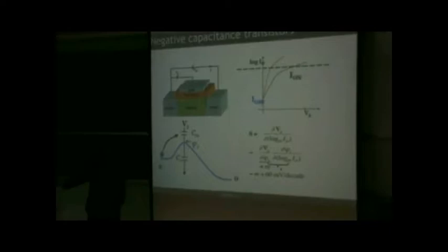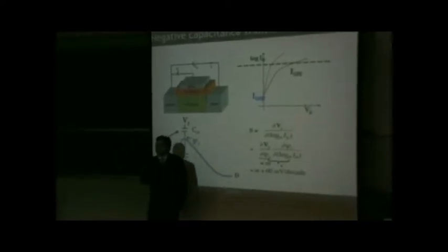Now, more mathematically, I can look at this equation, which basically tells us how the drain current changes as a function of gate voltage, which is defined like this and called subthreshold swing, right? Suman has talked about it, and Mark has talked about it, that there is a limit of 60 millivolt per decade. And this can be seen from here. I can write this as a product of two terms. The first term is del Vg del psi s, where psi s is a node voltage. So this is just the capacitor divider formula.